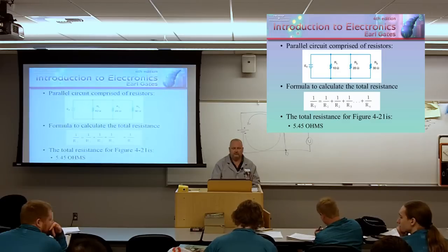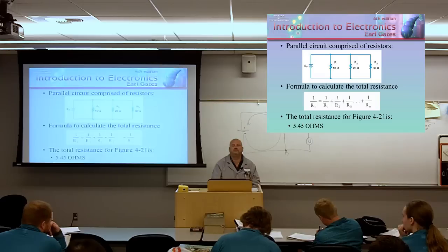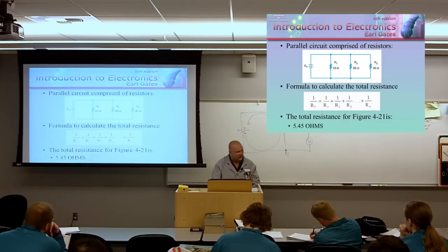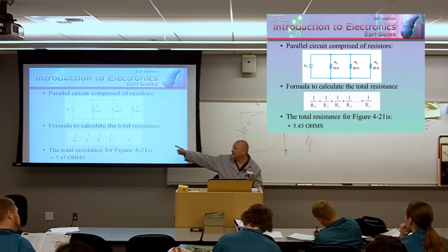I'm just trying to synthesize it into a formula now. Take the resistance of one resistor and divide by the number of resistors. Only if they're equal. This only works if they're equal. It's a thumb rule. You don't need to use the thumb rule. It's just another tool in your toolbox to make it easier for you. If you doubt me, well, you could always use that formula.